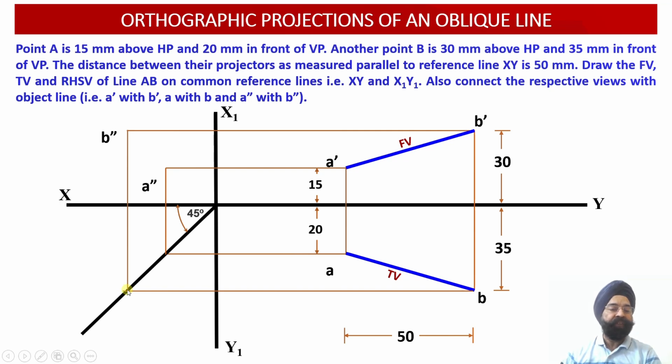So once we reach this point, that is, this horizontal construction line intersects with the transfer line, now a vertical projector will be drawn through this point B, and wherever this point B vertical projector line intersects with the horizontal construction line which we had drawn earlier through the point B dash, this intersection of these two construction lines will provide us with the location of the point B double dash.